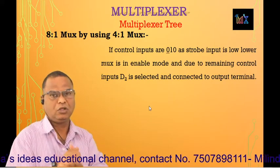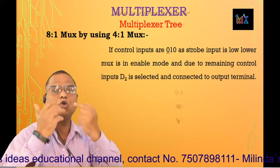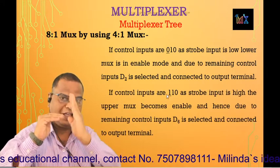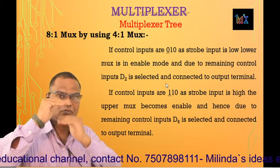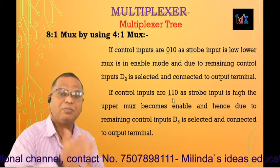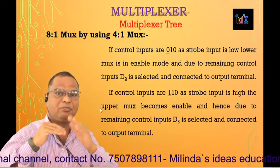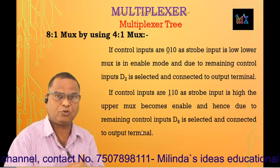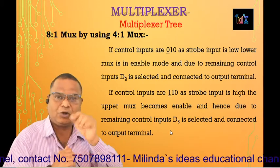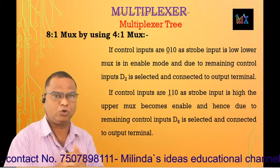But if the control inputs are 1 1 0, as S2 is 1, that means the strobe input is high, the lower mux is in disable mode while the upper mux is in enable mode, and as per the remaining control inputs, that is 1 0, once again the data connected to I2 is selected and fed to the output terminal.